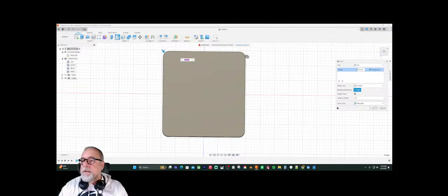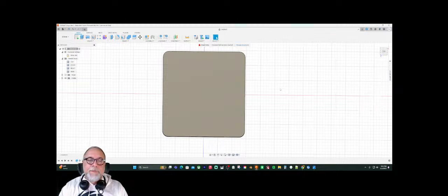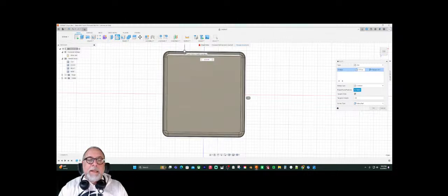All right. So we're going to say, yep, we like that. Now we're going to put that other edge on here. But now I need to get these corners as well, because I want them to have that same radius, because I want it to be nice and smooth all the way around. So same thing, control click to select. I'm going to do my radius again, pull this in, and now I can see what kind of a radius I'm going to get from that.